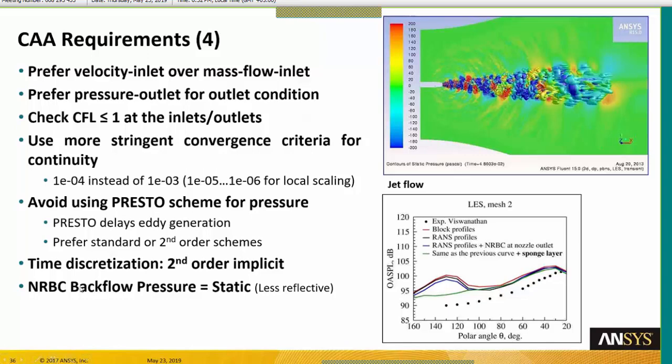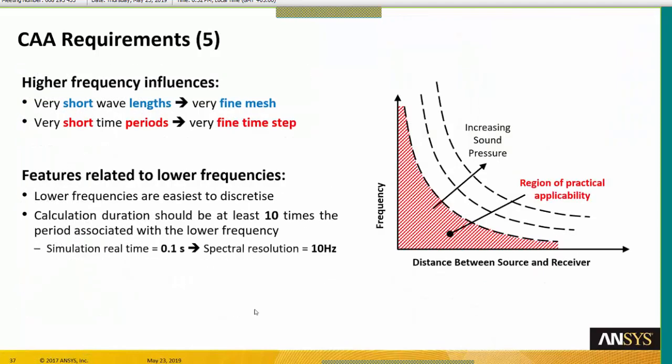And for a boundary condition, in this situation when you have a jet inside an atmosphere and you cut your domain at some point, prefer non-reflecting boundary condition. It's necessary if you don't want any acoustic information going back inside the domain. Sponge layer, yes, remember this one. Sponge layer may help to recover proper acoustics inside the domain.